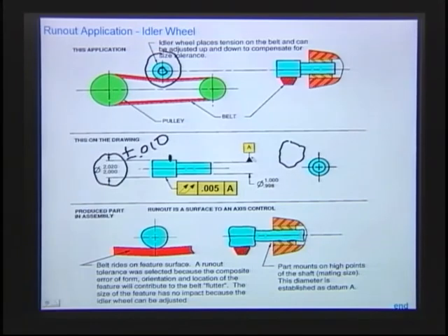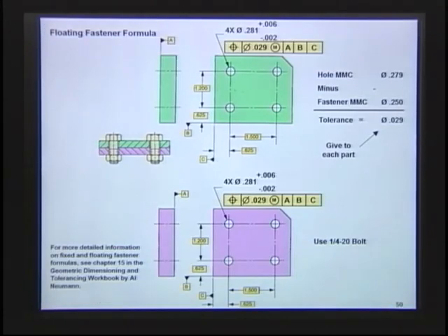When you come later on, I think you're going to have the mixer, and a few other parts that are going to have some shafts in them, and you're going to have to apply some tolerancing to them. All right, here are the fastener formulas. The fastener formulas are going to be important when you apply the geometric tolerancing to all of your parts. When you put a position on holes, and you put slots and tabs and things like that, you're going to have to calculate a position.